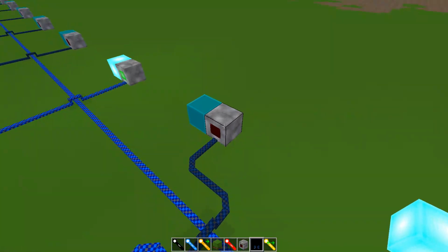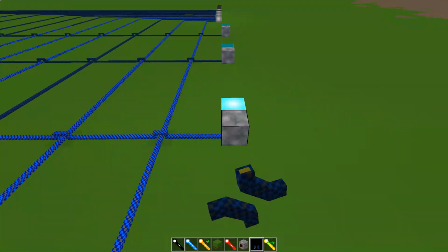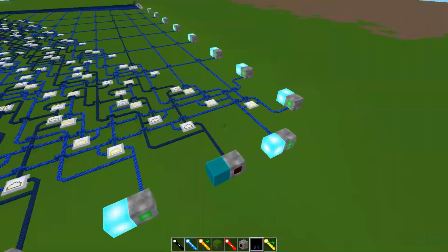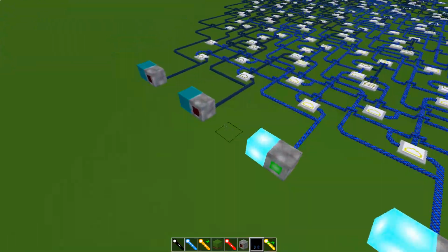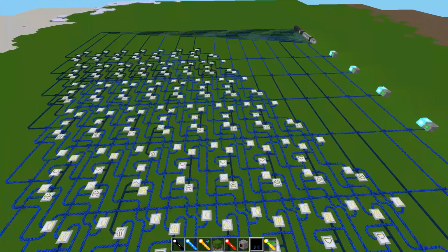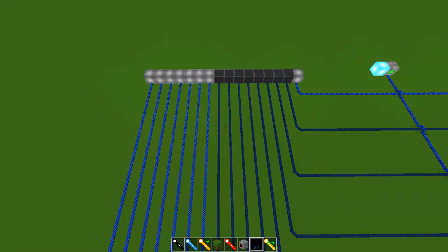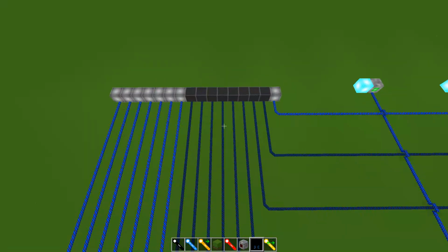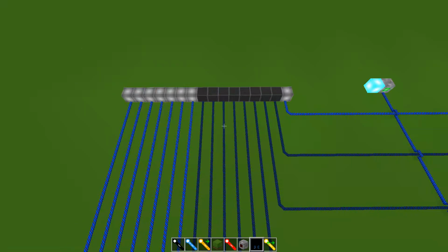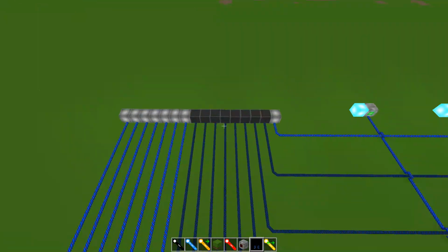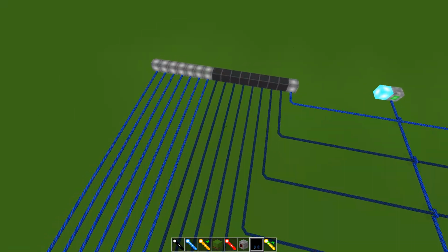I will also demonstrate what it looks like to turn on all of the inputs. So that is in hexadecimal FF times FF, and the correct result should be 7 zeros followed by 7 ones followed by 8 zeros followed by 1 1, and that is indeed what we see here. This is the highest possible number that can be outputted from this circuit. It cannot be anything higher, that's the highest value.